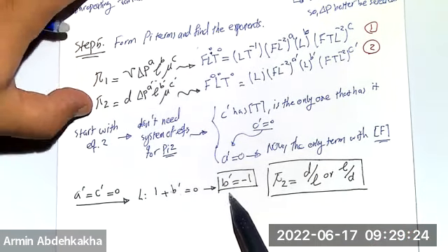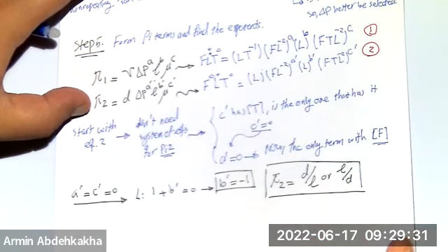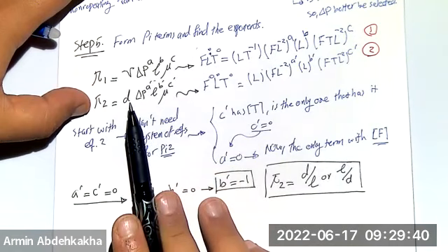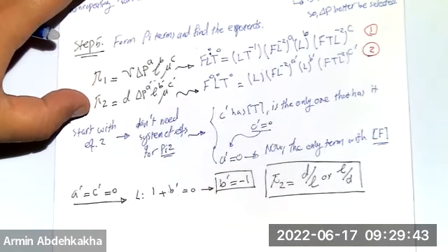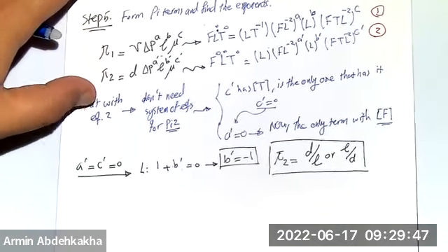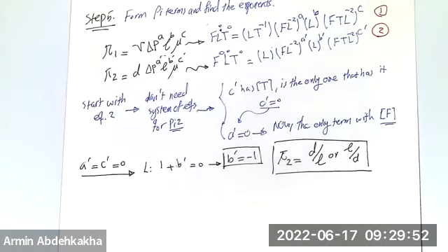It doesn't matter that you find B prime equal to -1, because it's a dimensionless term, and you can just decide to write D over L or L over D. It means it's possible to choose L instead of D as your independent variable. That doesn't change anything, so you can decide which one you want to write. Both of them are correct. That's for pi 2. Okay.